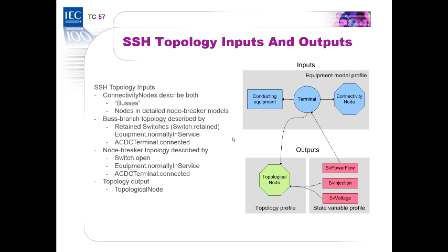Node breaker topology is the same thing with the equipment in service and the connected flag, but you also have the switch open. So the topology processor will have to look at all these three attributes to actually determine if something is in operation or not.